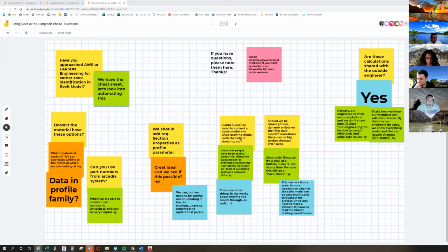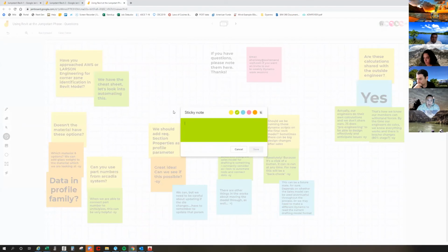So those do change reinforcement requirements sometimes. We may look at it, and at a typical 5-foot module, we're okay, even at the corner zone loads. And then they take that 5-foot module and make it a 7-foot module at the corner just to make that unit simpler, or just to make it a single unit. Now you've got a 7-foot unit, and that changes some of that criteria.